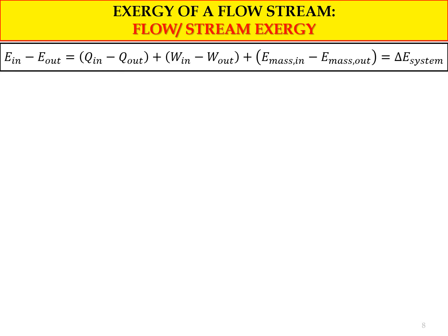Exergy of a flow stream. Flow stream exergy, which is for the open system, control volume. Okay, we already looked into the closed system and we already developed the equation of the closed system. Now we look into the open system. First, we look into the fundamental equation, which is the energy balance equation. And here we should consider all of the terms, which are Q in, Q out, W net in, W in and W out, and also mass in and mass out.